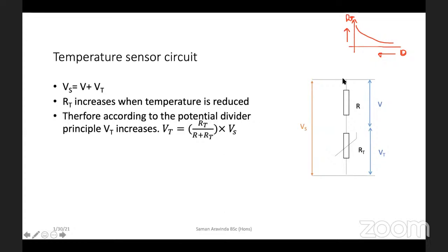Right. So the resistance of the thermistor increases, and the share of potential difference across that also increases. Now, say that you have a heating circuit. For a heating circuit to work, say it needs, with these arbitrary values, 10 volts. Now the supply given is like 20 volts, let's say.